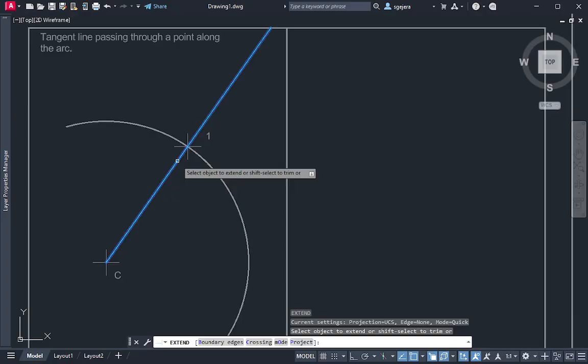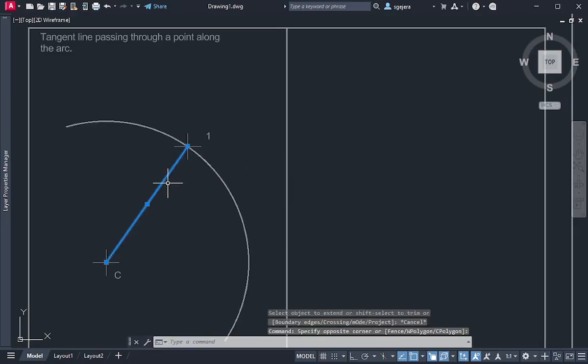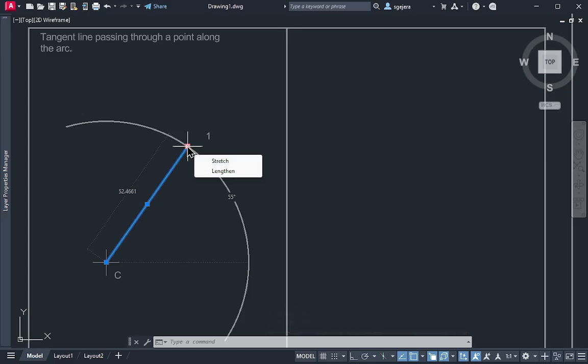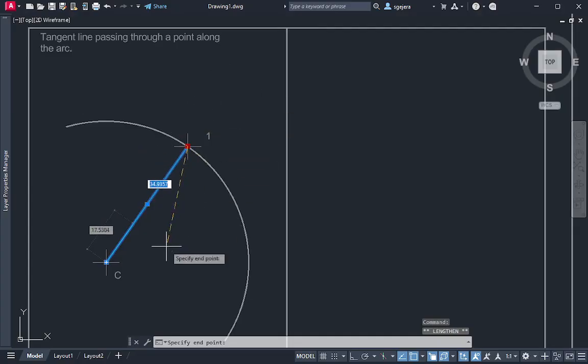Which is, in our case, yung borders ng worksheet yung hinahanap niya. So, kung gusto nyo kontrolado yung amount na ile-lengthen nyo, you can actually select the line, grab one of its endpoints, hover nyo lang, tapos may lalabas na option. Either stretch or lengthen. What we want is the lengthen option. If you click the lengthen option, you can now lengthen the line freely, no? Okay? So, eto, malilengthen ko siya ng ganyan.